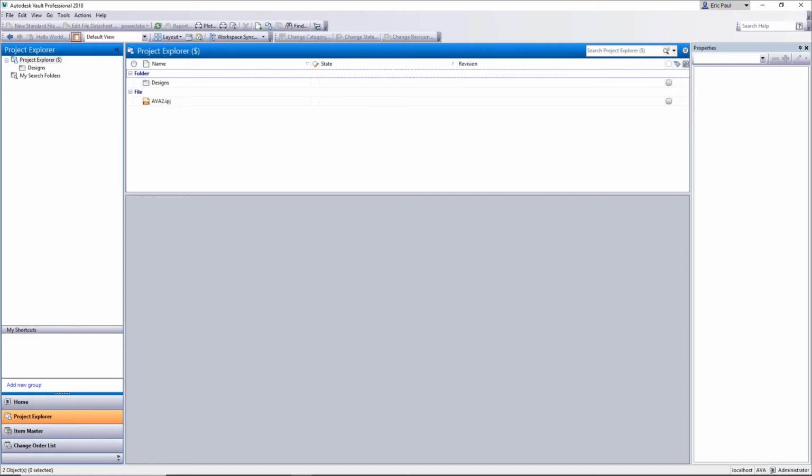No, but yes. I need a little bit more detail there, Dennis. If you're using Inventor 2018, you definitely can't use Vault 2016. Vault has to be the newest program or equal to the newest. So Vault has to be 2018 if Inventor's 2018, or if you have Inventor 2017, you can use Vault 2017 or Vault 2018. Vault just has to be equal or newer than the actual CAD tools.